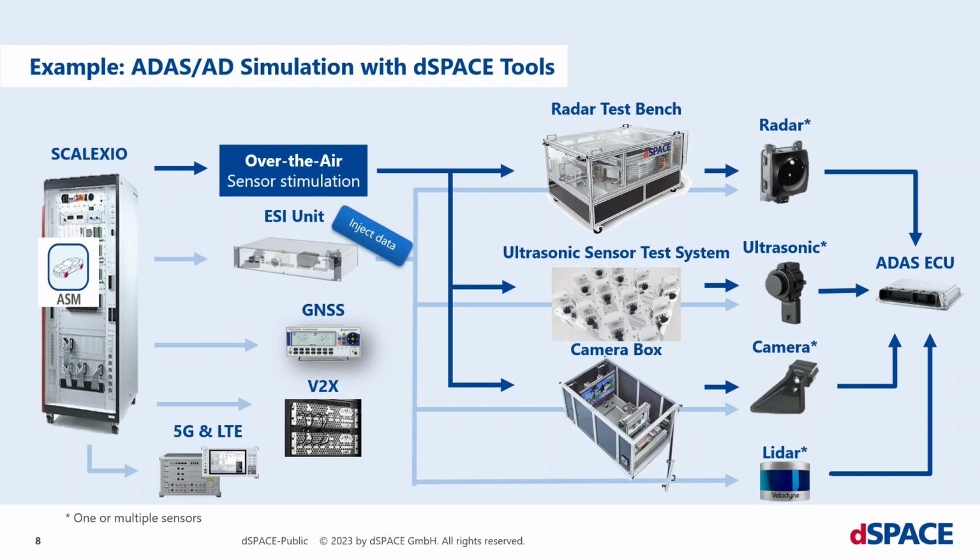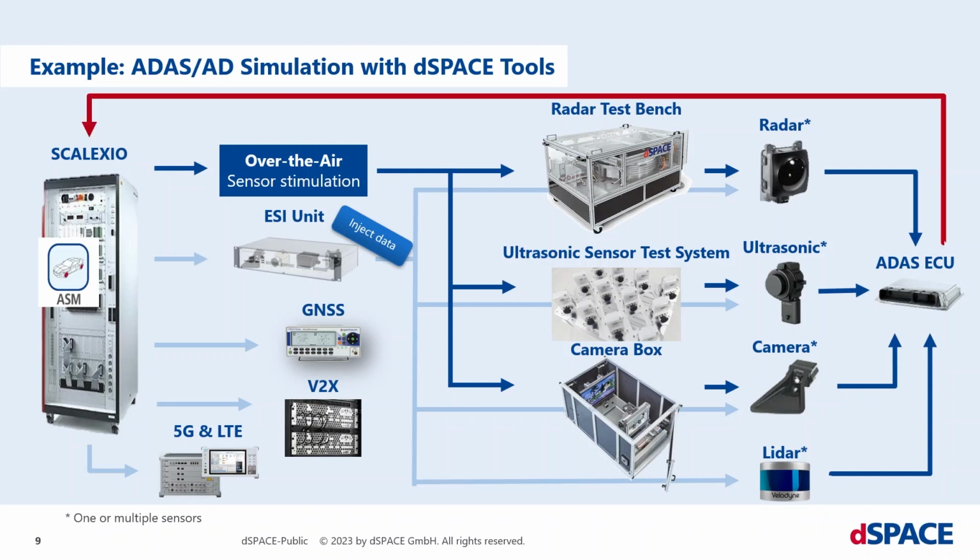Together with GNSS simulation and different V2X solutions, the complete vehicle environment for a central ADAS ECU can be simulated. All of this is synchronized with the traffic and vehicle simulation that is running on our real-time PCs Galaxio. And to close the loop, the feedback of the ADAS ECU can again be fed back into the simulation to include the actions of the system under test in real time.